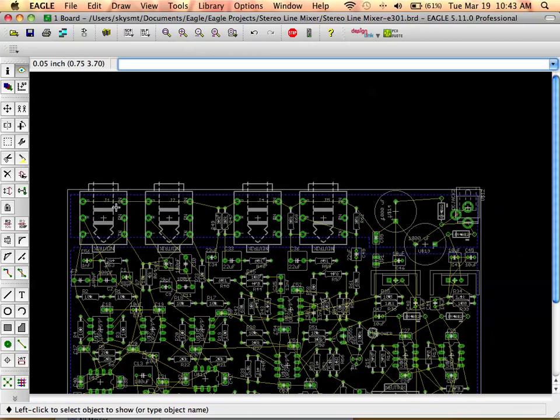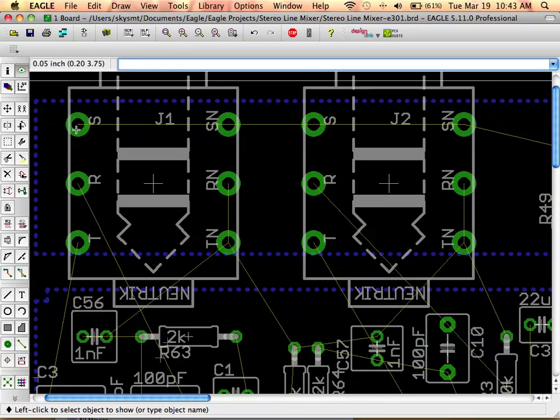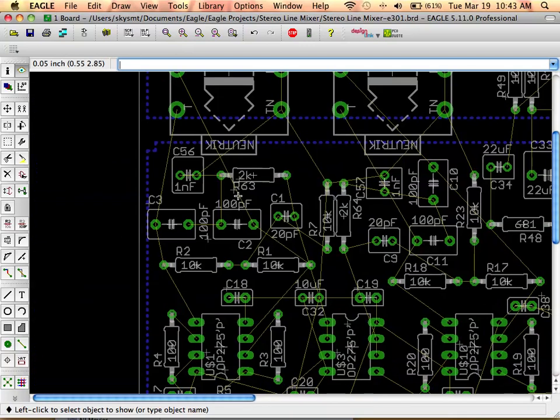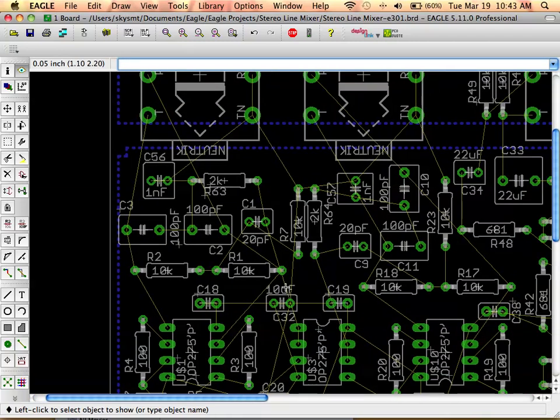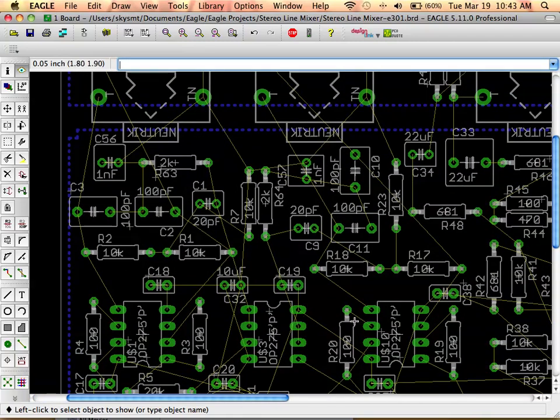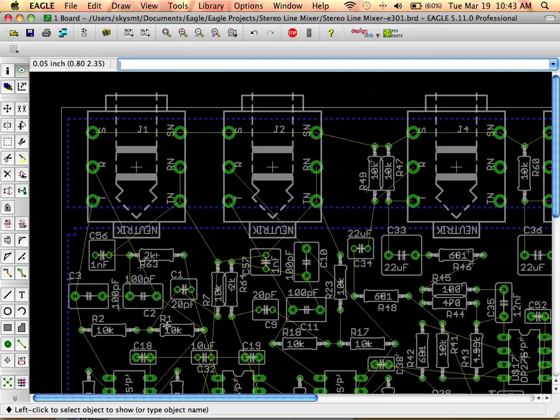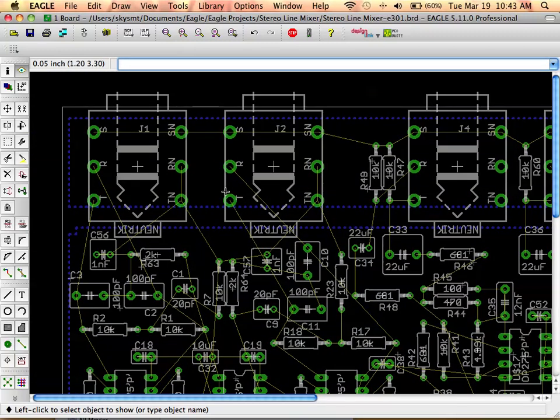So what you can do is, instead of running that ground current and letting it infiltrate your ground pour where all your circuitry is, right? Because if the ground pour next to all your op amps is fluctuating and has noise voltage on it, then that's going to couple into your signal path based on the output of your amplifying stages. Okay, and that can increase through the more stages you have. So instead of having it do that, this is just a very nuts and bolts way of not letting your ground current, this noise current, infiltrate this part of your circuitry.